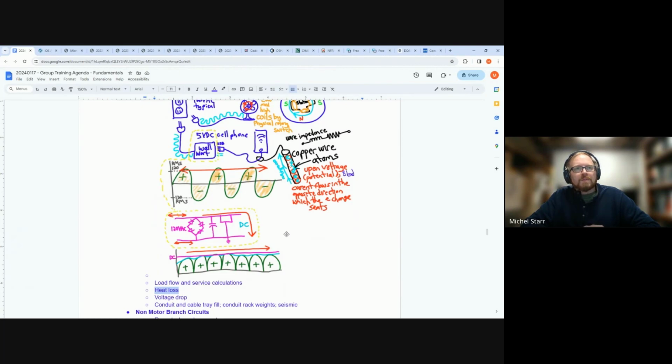For that sake, for instance, the code requires for dry type transformers, although the insulation levels are high enough and usually it doesn't require it technically, it might require the room to be fire rated, maybe a 1 hour rating. If you get over 35,000 volts and you need a transformer vault, that's a whole other situation, like a 3 hour rating. If it's an emergency room, you might also have those concepts, but we're getting into the fire rating of the room when I was discussing the heating.